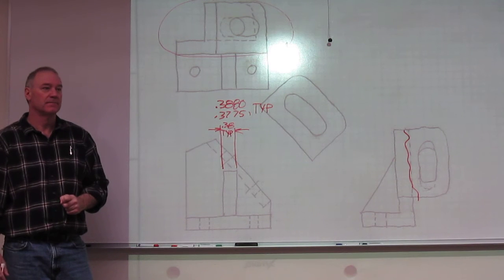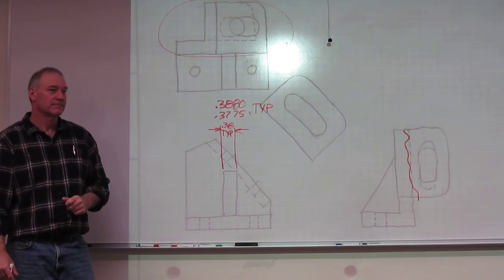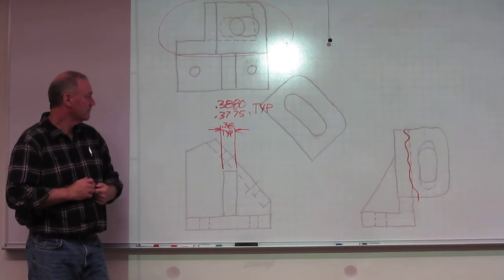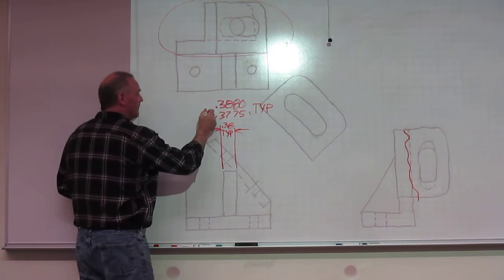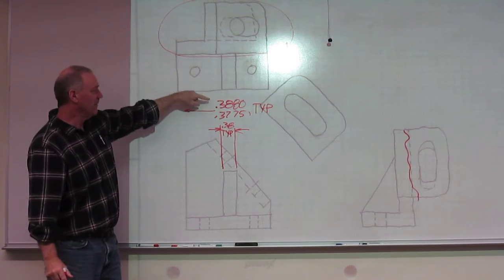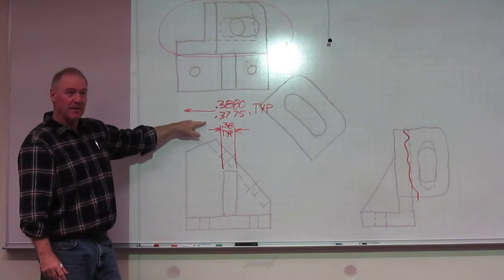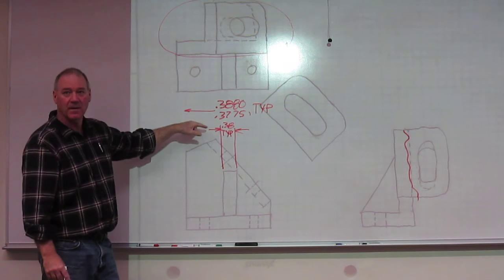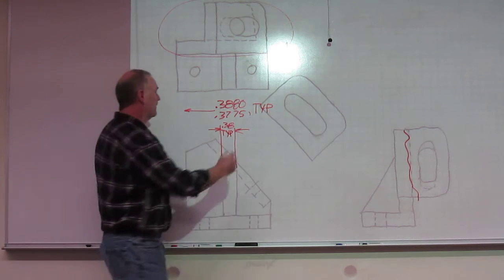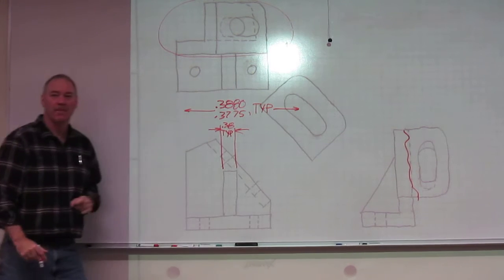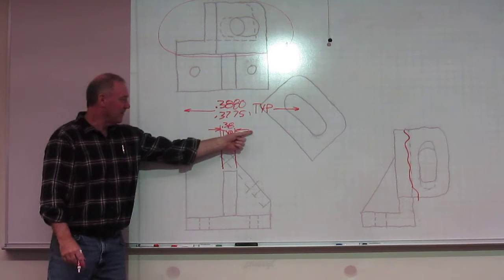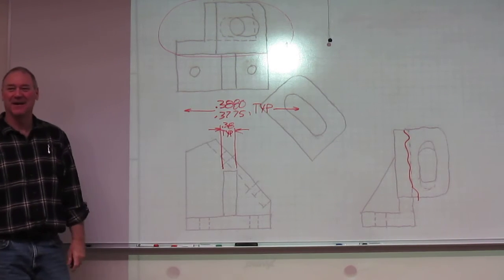Do you put the comma in the normal, the short way, 0.38 comma? Or is it 0.38 comma? No, because remember, there's an extension dimension line here. At center, when we do limit dimensioning, we bring them up and down, where my upper limit is on the top, my lower limit's on the bottom. By the way, it's wrong in the text. And then I would center the typical on my dimension line. Yeah, so there's another dimension line right here. On that instance, I'd be pulling it out right over here, because I can't get that in that distance.